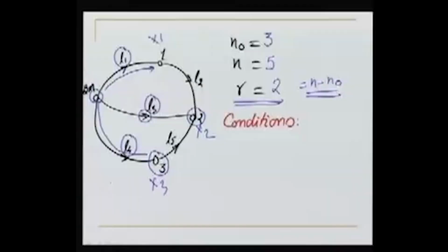And L3 is the difference in elevation between point 2 and the benchmark. It's a closed loop. So using this closed loop, we can write one condition equation, and that condition equation will look like L1 hat plus L2 hat minus L3 hat is equal to 0. Now please mind it, I have put an arrow here. That arrow shows the direction, or that this is the positive observation.